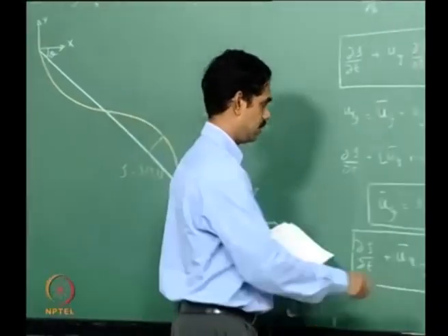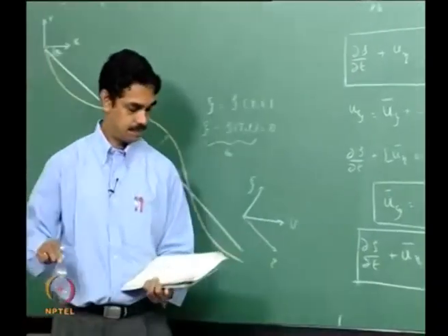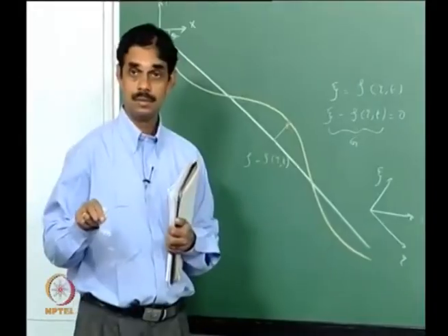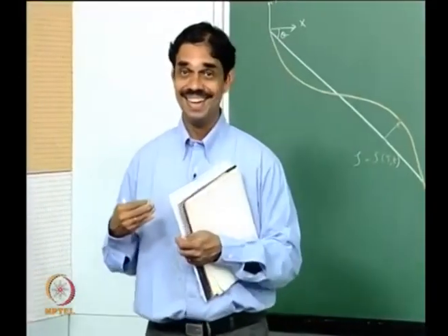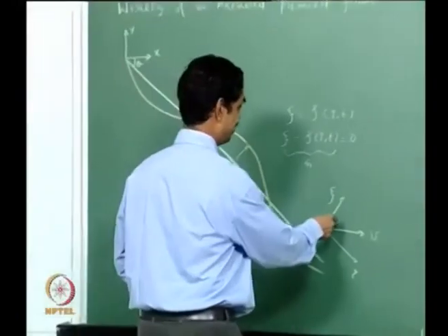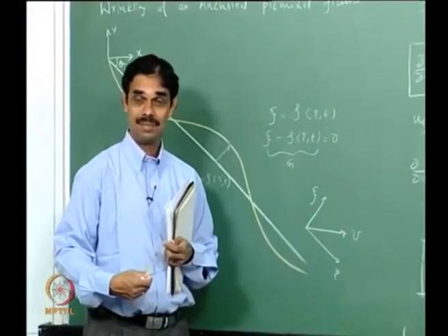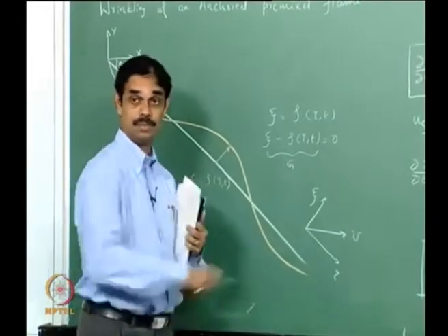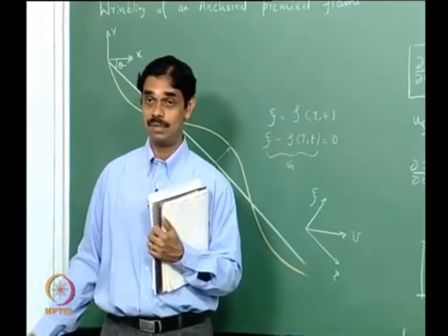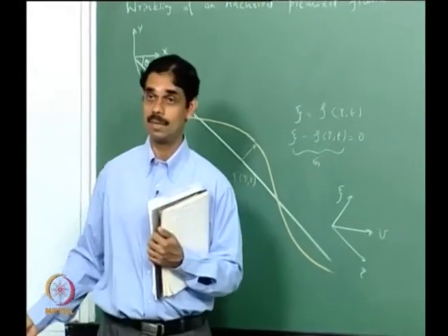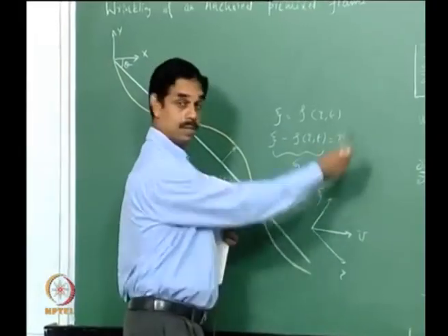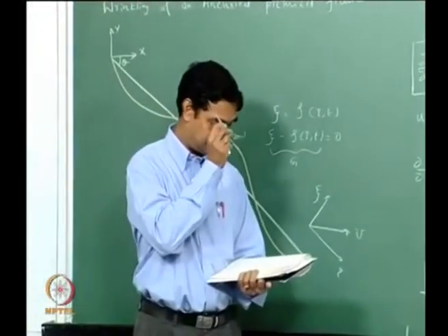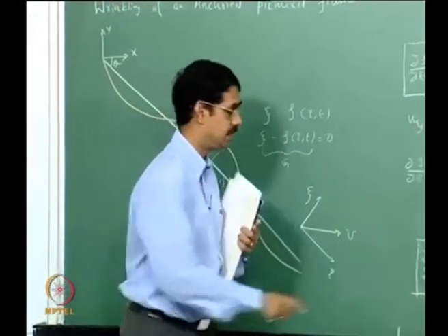So what is u psi prime? Yeah, what does this mean? It is the direction normal to the mean flame shape. So we are being forced by a velocity in a direction normal to the mean flame shape, right? I mean, so if you have an acoustic field, it has a certain velocity and pressure. The velocity has a component normal to the flame shape, and that is working as a forcing term. And what is the physical meaning of this equation?